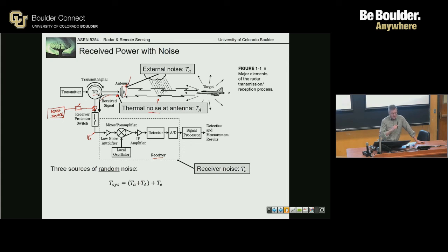Again, maybe in the systems that I'm used to, there's so little loss between here and here. Well, we do have cables and we calculate the loss. So if you do it from a signal-to-noise ratio aspect, or a noise figure, most of the time you put the noise figure reference at the LNA input. Yeah.